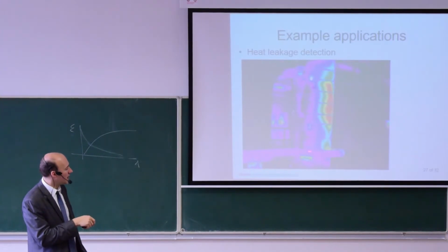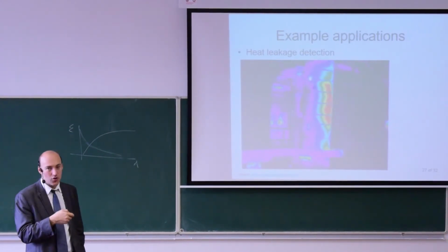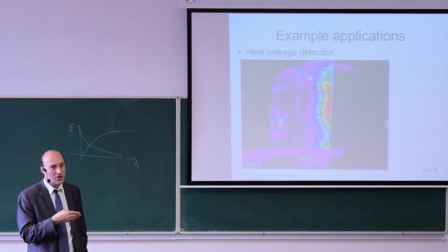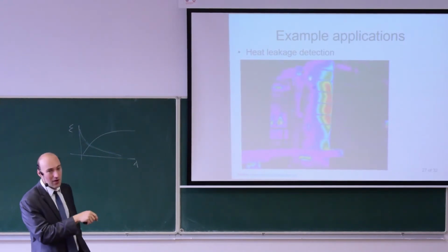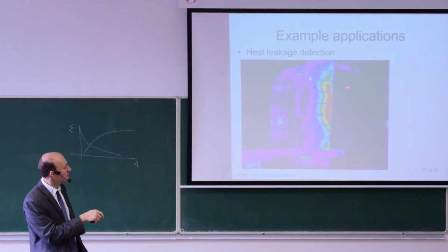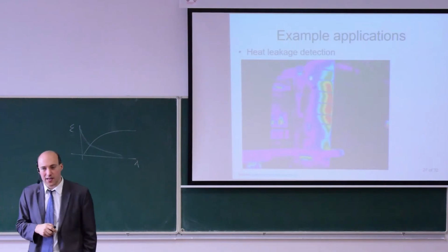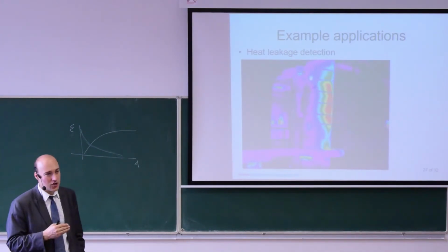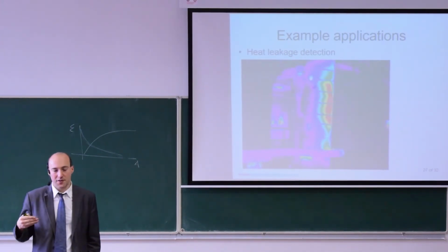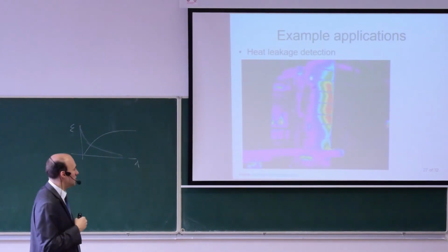If this were a metallic pipe, then you should also look for other heat sources that may be in this area, like this. So this may not be a leak, but it may be a reflection from some other pipe that is nearby, or from some other machine.